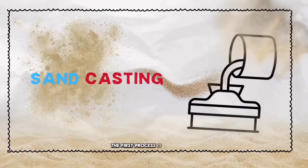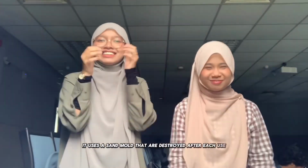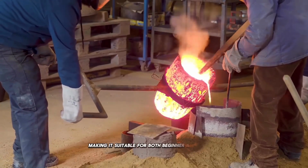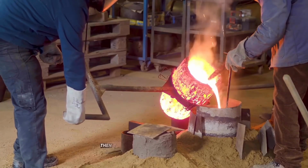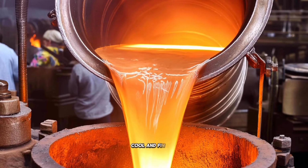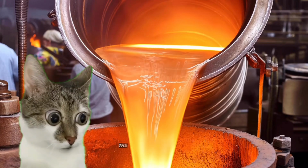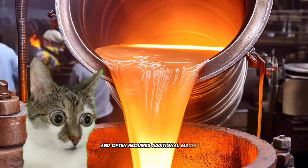The first process is sand casting. It uses a sand mold that is destroyed after each use, so the mold cannot be reused. The process is simple and flexible, making it suitable for both beginners and industry. The steps are: first, a pattern is made, then the sand mold is prepared around it. Molten metal is poured into the cavity, cooled, and finally the sand mold is broken to remove the casting. The surface finish is raw and often requires additional machining.